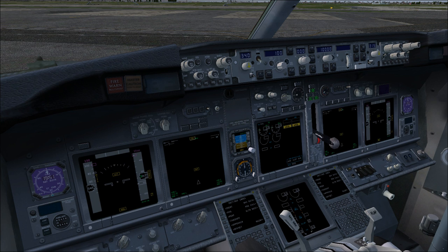Usually the time to align the IRS is greater when you go to higher latitudes, on the south part of the world. At this point, as you can see now, the copilot screens are also on, and so we have powered up the AC power for those screens.